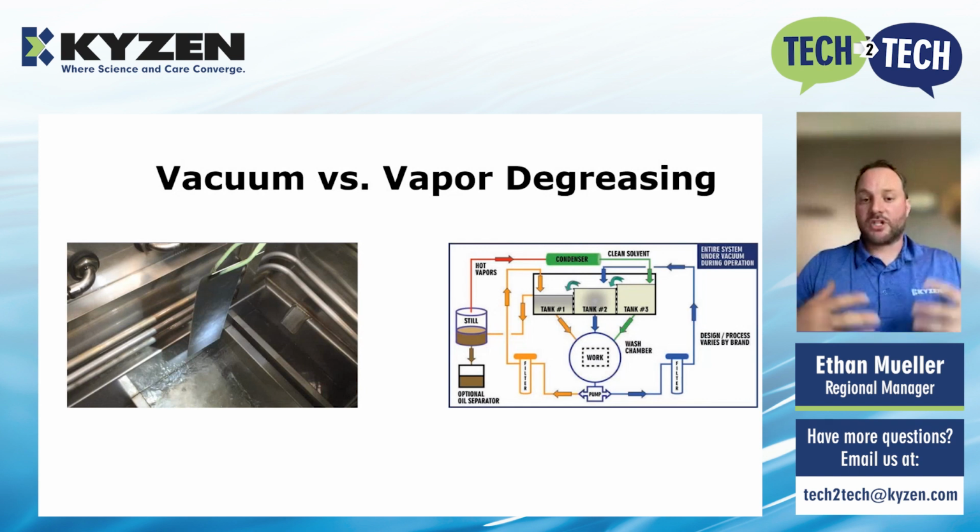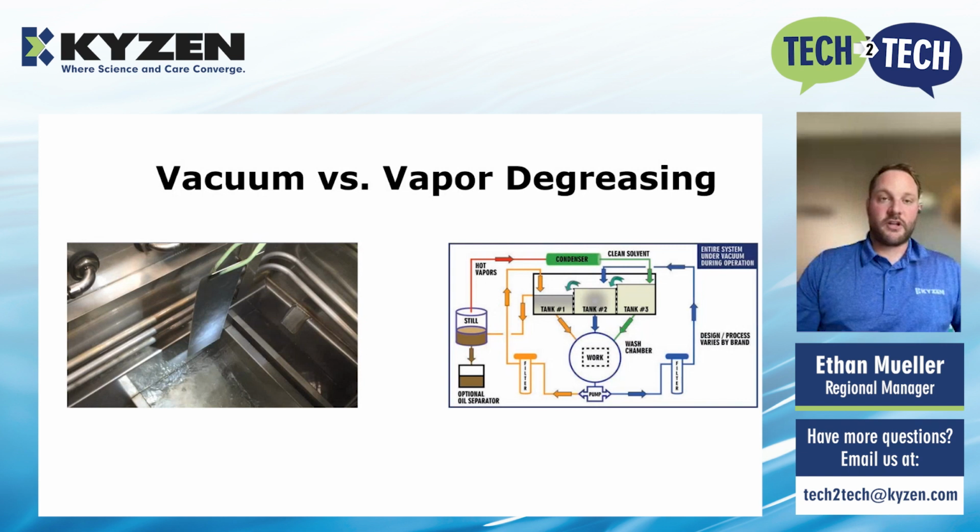And they also have a much higher boiling point and are less volatile. So that type of solvent cleaning is relying on the vacuum to actively pull that solvent away from the surface of the part, which, even though it has a little bit higher of a surface tension, a little bit less volatile, higher boiling point, it still tends to dry better. These systems tend to dry better than an aqueous system.